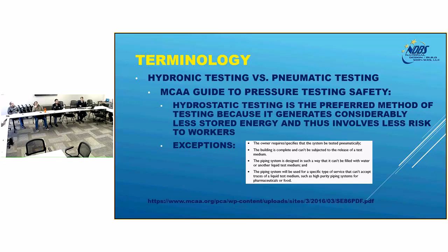If you have a high purity compressed air system and a low purity compressed air system, we hydrostatically test those systems in the pharmaceutical business. But you have to dry them out with nitrogen. So there's a purge time and a dry time associated with that testing. Clean systems, on the clean side of compressed air, you typically use DI water to test that.